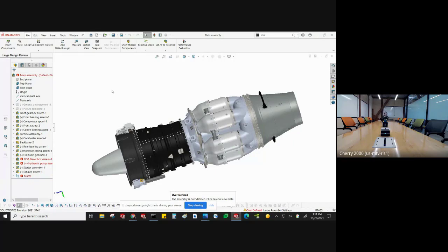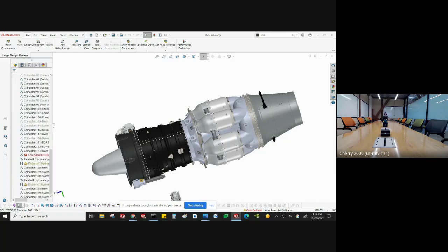And the reason that is because if you've got a flexible sub-assembly, it has to actually solve the location that it's in. All I'm looking at here graphically right now is how this thing was last saved. So it hasn't been rebuilt or anything like that. I'm just jumped in there. But when I chose to edit it, it did bring in some information that I didn't have previously. One big thing is I've got all my mates here.